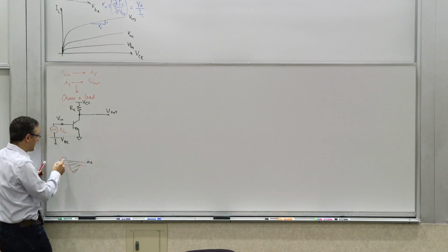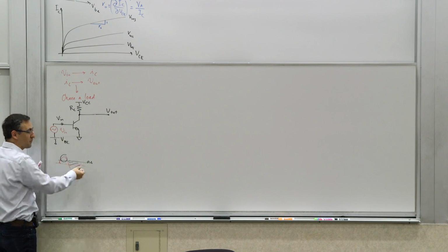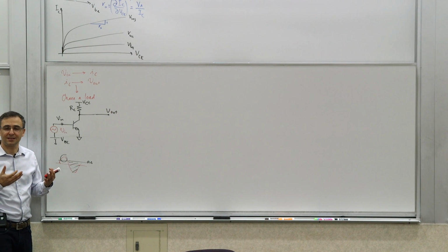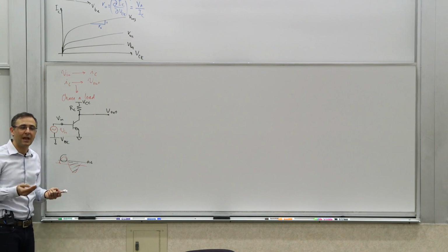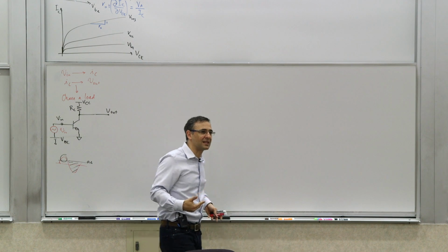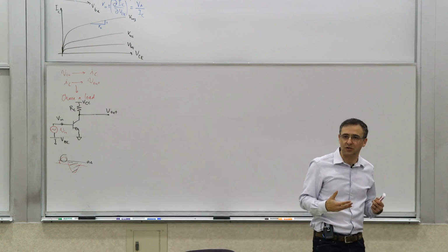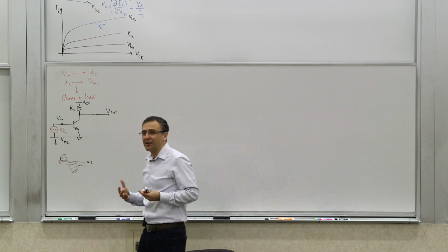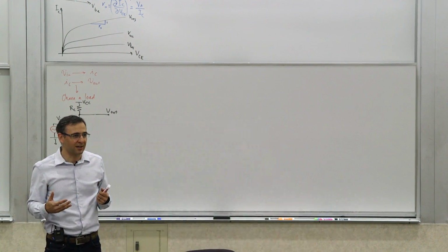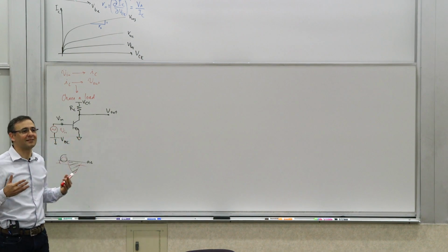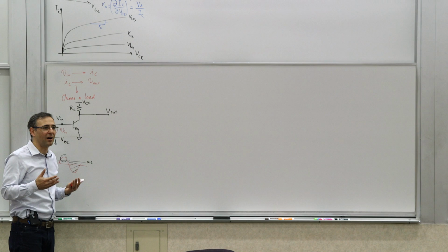So you will see some fluctuation around here and nothing over there, or very little at least. This is called biasing, and we'll talk about it more extensively, in multiple stages, becoming more and more sophisticated with the biasing of the stages. It's an important part, and when you design, a lot of people have the most trouble with it. When we get to our project, one of the first things you need to get right is to get the transistor biased properly.